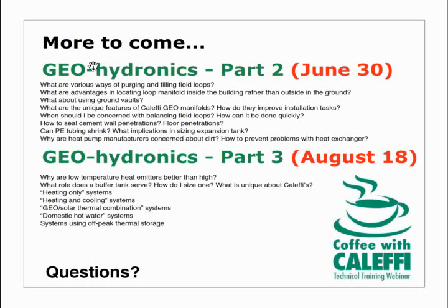I think that's referring back to that pond system that I showed. Again, you want to be generous in sizing that heat exchanger. I would say probably the approach temperature difference no higher than maybe 5 degrees Fahrenheit. We don't want to impose much of a thermal penalty between the water temperature that the heat pumps are seeing and the water temperature from the source.